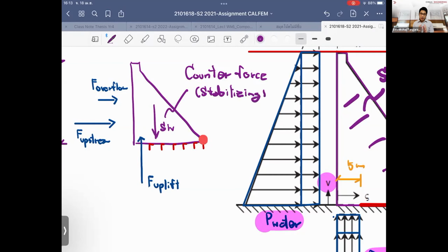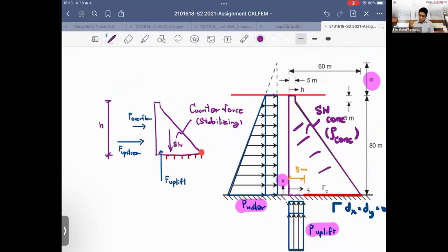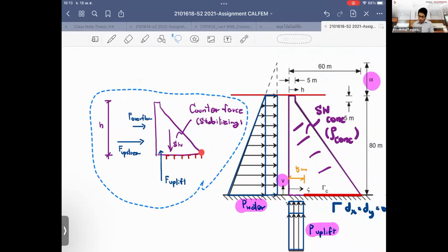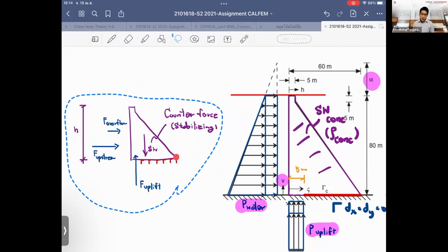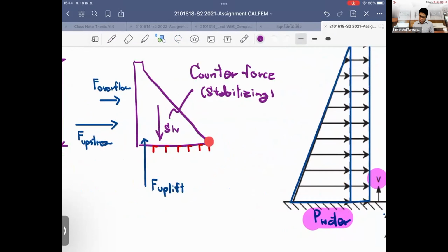If you read any of the books that suggest how to simplify the dam problem, they say you should simply use these diagrams and make sure that this force is high enough to resist this type of force. And if you're sure that the self-weight of the concrete is good enough, no overturning is going to occur, because you just make the equilibrium of the resisting force and the acting force, so it doesn't cause you the overturning problem.